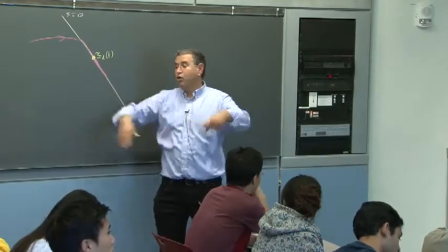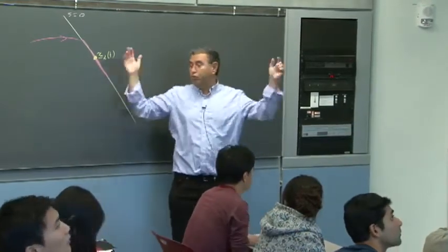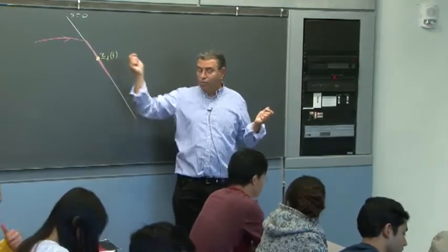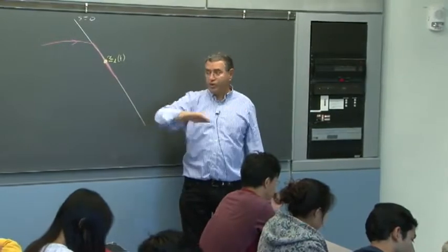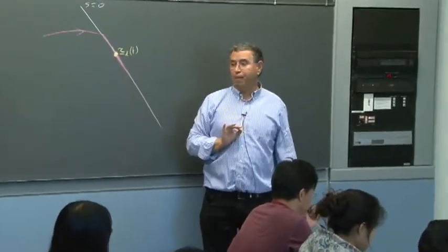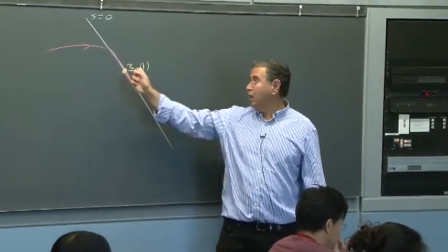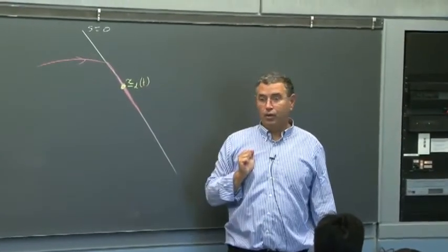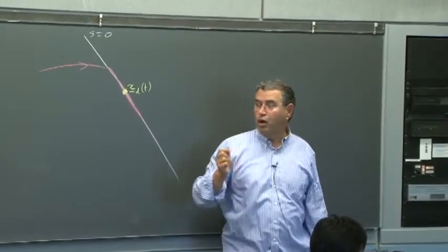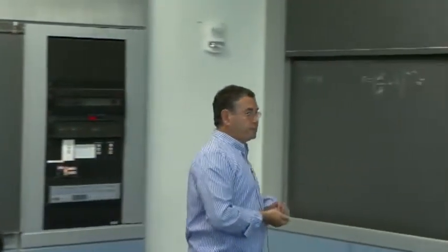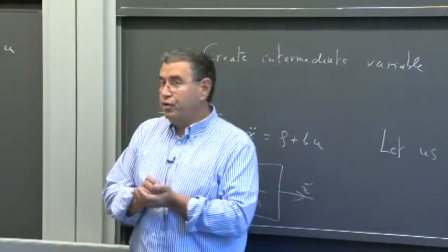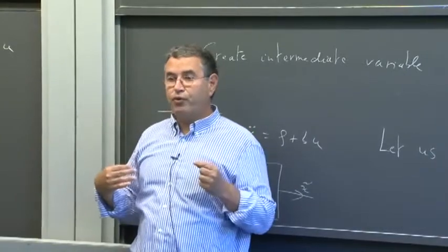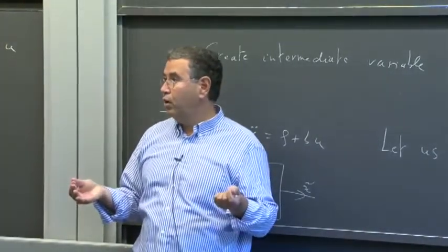So it's not that you're on this hyperplane and you drift on it or whatever. Because this hyperplane is given by S equals 0, once you're on this hyperplane, you know exactly what happens. There's one trajectory that happens, and that takes you to xd. So introducing this intermediate variable says we replace an nth order problem by a first order problem.